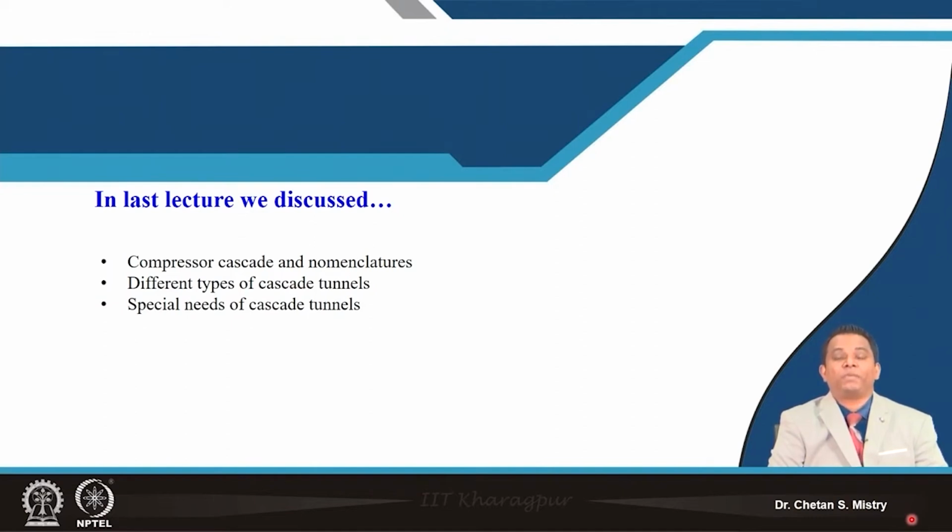At the same time it has its own benefit. The flow on the blade or aerofoil is initially laminar. At about 30 to 40% of the chord, the flow is of transition nature, and later, towards the trailing edge, the flow is turbulent.